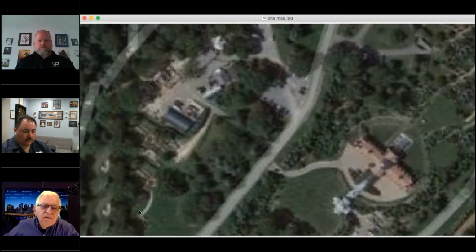So we didn't cover all the way into the green room, but from the truck compound here, we used a Yagi antenna on one channel, one output of a transceiver, and aimed it south. And then over here in the announcers booth area, we put a Yagi antenna outside the room, shooting toward the truck compound, and another Yagi antenna and another transceiver shooting toward the venue. So we were able to cover this entire area without any dropouts whatsoever.